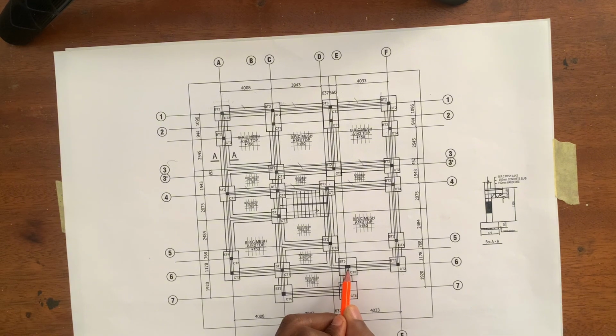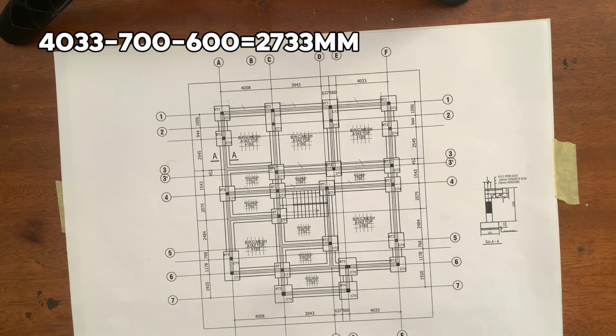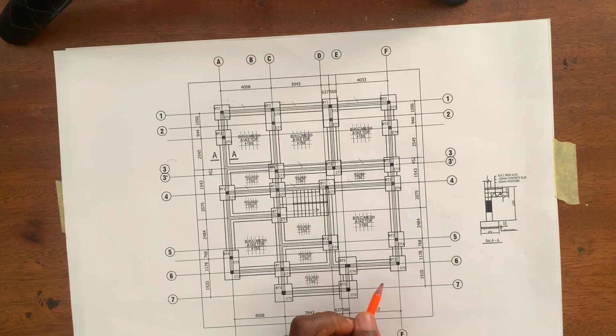So we can now minus 700 from here and 600 from here. It's going to give us the dimension from here to here. So 4,033 minus 700, which is half of base type 5, and then minus the half of base type 2, which is 600, will give me 2,733. So the dimension from here to here is 2,733. So we can now book it.